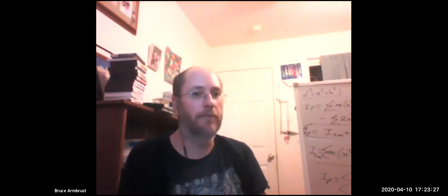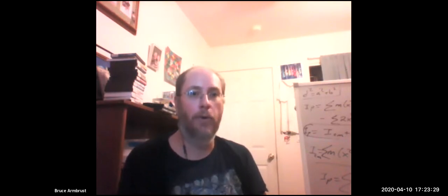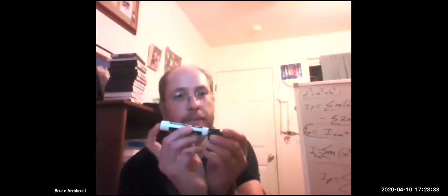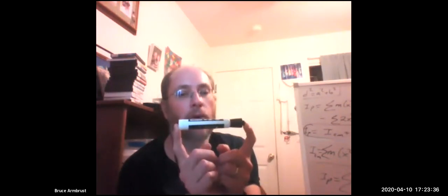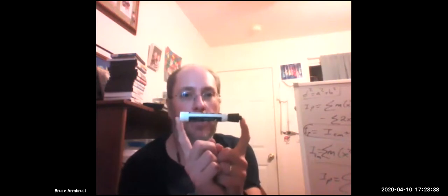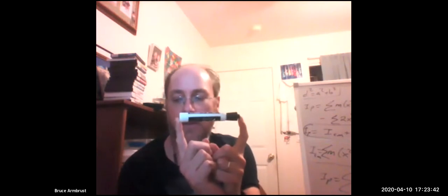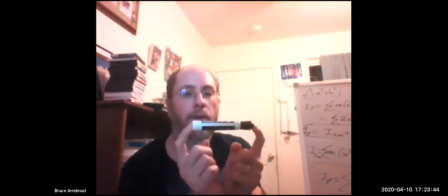It makes it super fast, Bradley, is really the whole point. Let's take this pen. A pen, like a rod, is going to have a different moment of inertia than a cylinder. The moment of inertia of a rod would be 1/12 the mass times the length squared, because we're dealing with something that doesn't actually have another dimension.